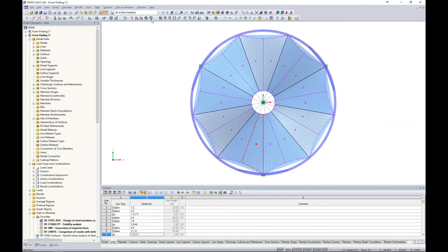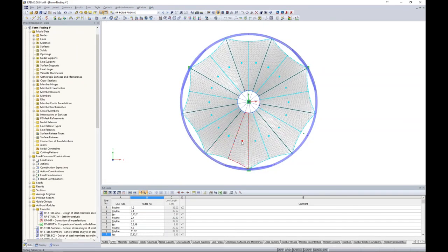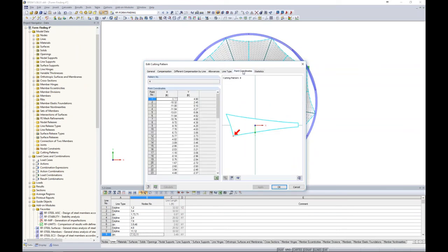So now that we're done with all of our input, we can click Calculate. Now, what I've done is I have an additional module here that I can launch because what I've done for all of these different 2D patterns is I set each one to have its own border and allowance additional width to it. And then I ran the calculation for all of my different patterns. So now we get a couple different tabs up here, which is our 2D cutting pattern. And once we run the calculation, we get the X and Y coordinates for our 2D pattern here. Now, this is a table, and as I scroll through this table, it is synced up to my little graphical view over here on the right. I can always zoom in, and it's all based around my origin right here at the center about what these X and Y points are.